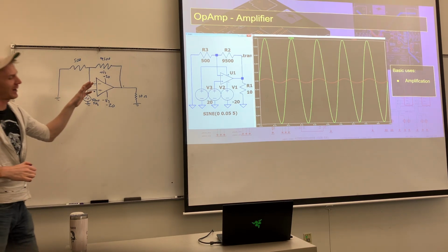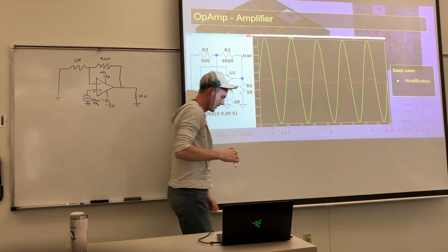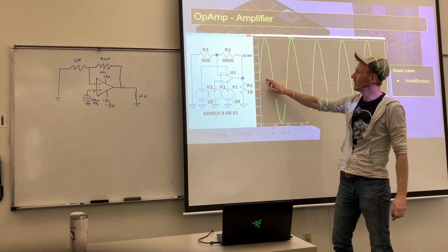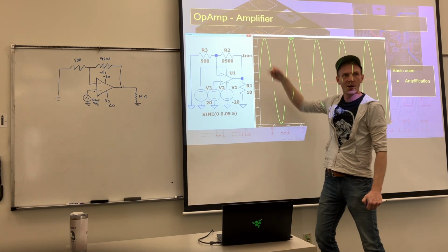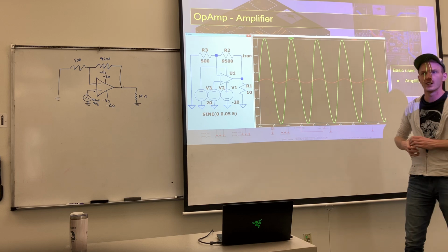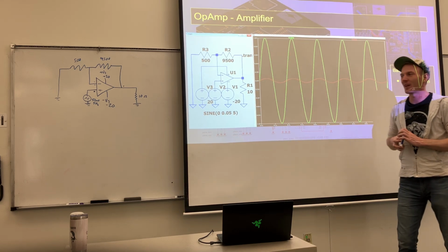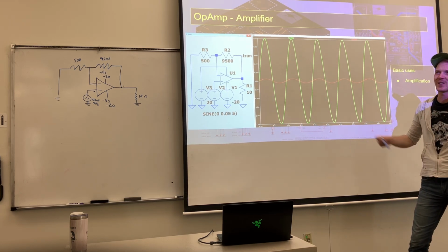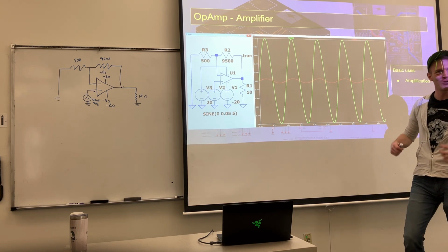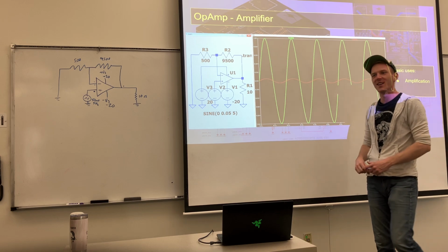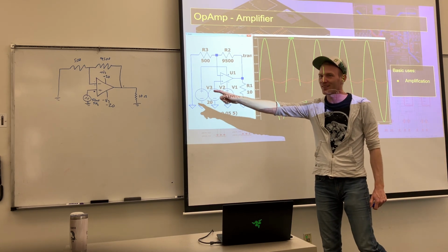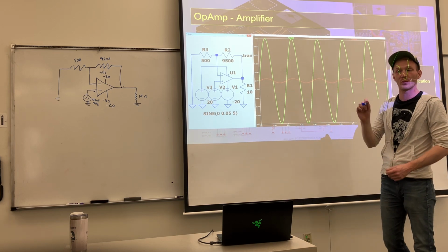And we can see that by waiting until we get to the peak. So we see the same 50 millivolt input. We get to 50 millivolts, 20 times that, 1 volt output, which is kind of crazy, right? Look at all the ways they teach you about op-amps, they're always like, they have infinite gain, you can just make energy out of thin air. And it's like, well, no, if I tried to amplify it more than Vs, it would stop at Vs, which we'll explore later.